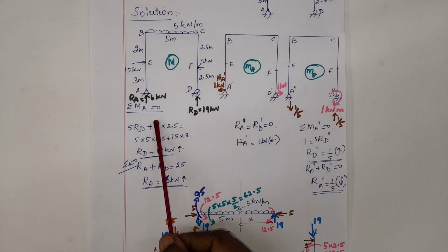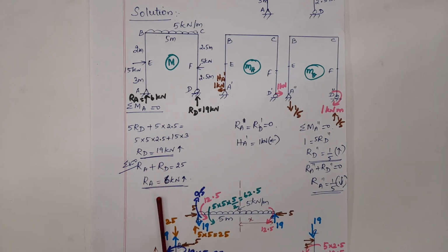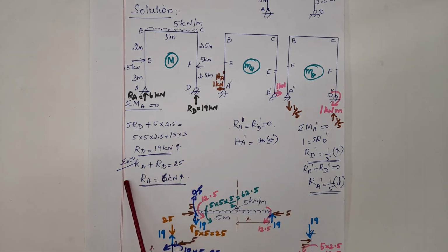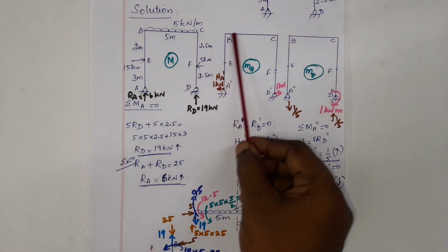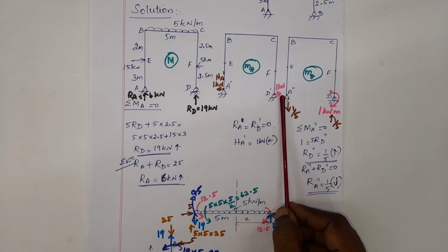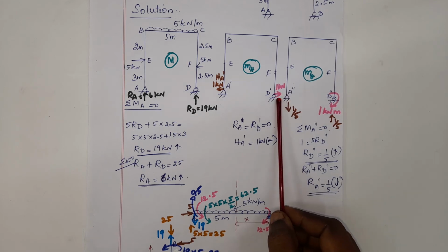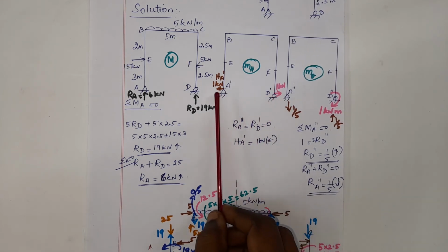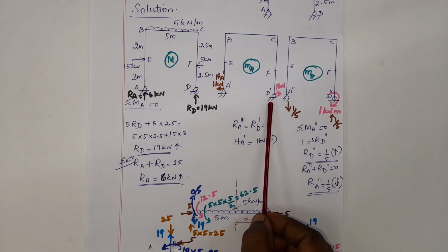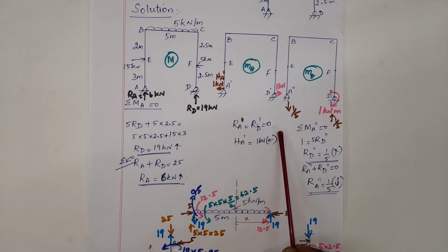We make use of these static equilibrium equations to determine the reactions at the support. So with the given loading, we have taken moment about A, we have applied sigma V equal to 0 and then determined the value of reactions at both the supports. Here we have removed all the given loading, applied only a unit load at D because deflection has to be determined at D in the horizontal direction. Due to this, the reaction is determined. So HA is possible, equal and opposite. Sigma H is equal to 0 is the equilibrium equation used. Since the horizontal load is at the support, there will not be any vertical reaction at the support.